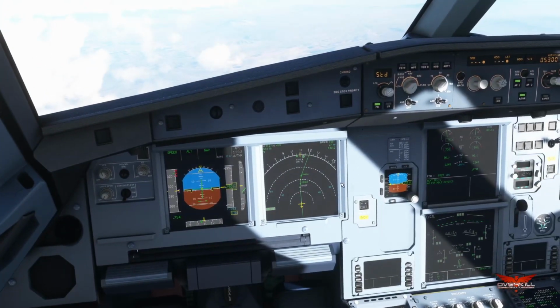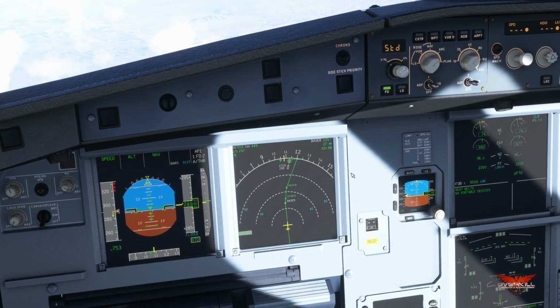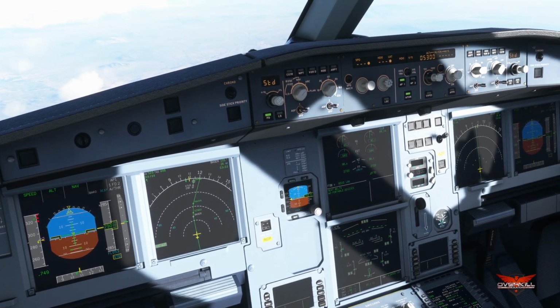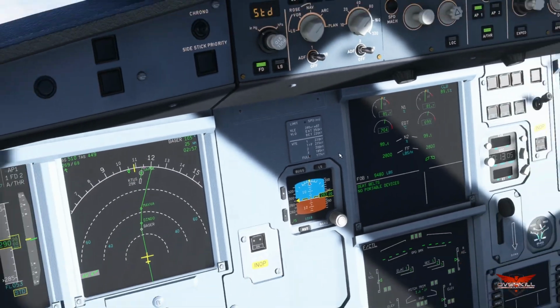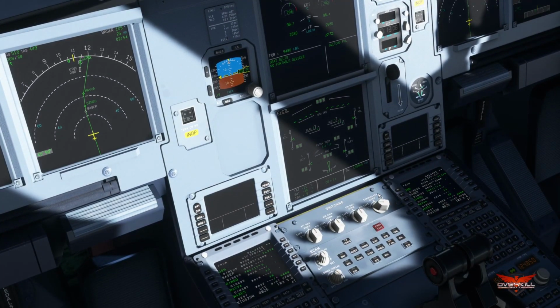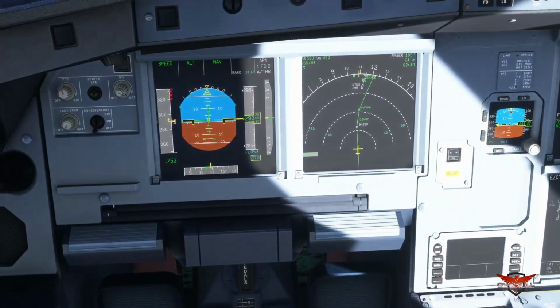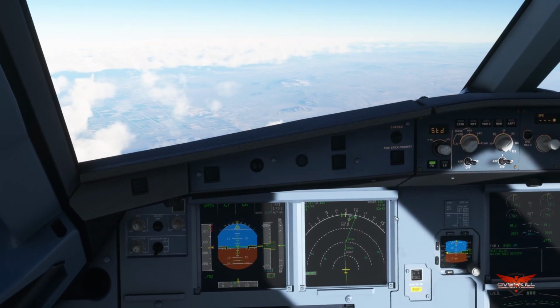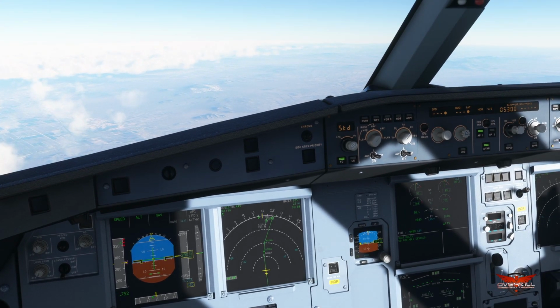Back to our flight plan. Let's see where we're at as far as our descent. It is imminent. All right, looking good. We're going to be setting our auto brakes to low for the approach. Some of the stuff we're doing very early, but it saves a bit of time. Again, we're a one-man show here, right? All right, and there's the initial fix. Let's go ahead and begin. We're just going to go into a managed descent.